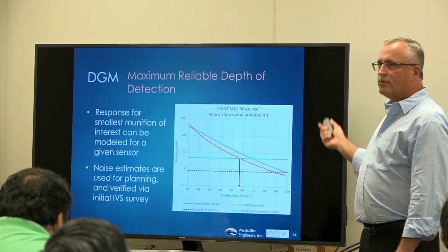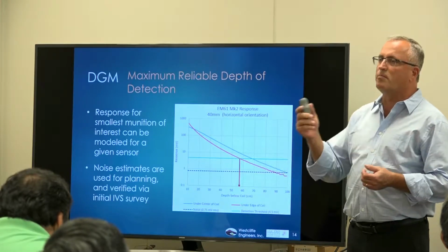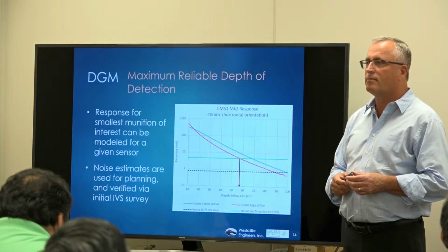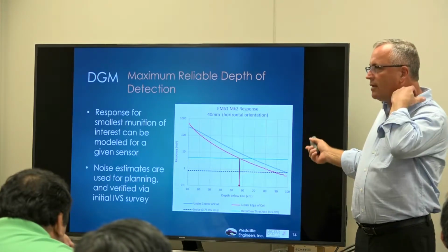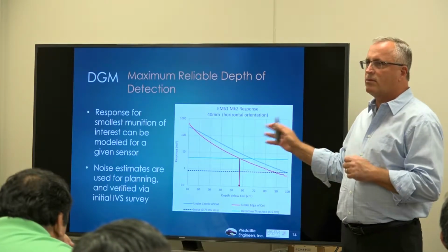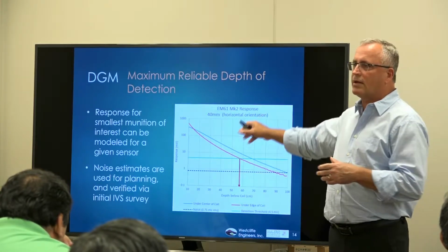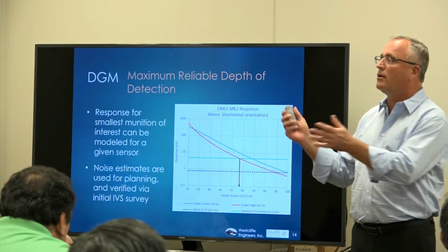The problem with the noise here isn't just that it's noisy so you pick more targets, it's that the noise can mask a target. Does that noise affect the AGC differently? No, well, you can't detect it, you can't do AGC, right? AGC will not see through the noise for you. Noise is noise, and that's a limiting factor. It's a limiting factor that has to be solved before you think about AGC.